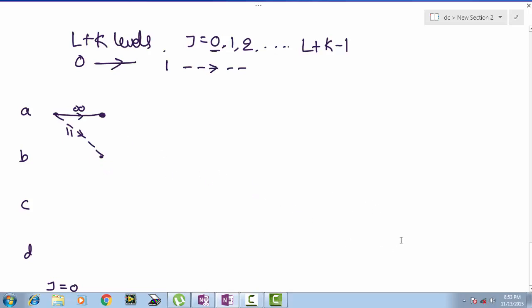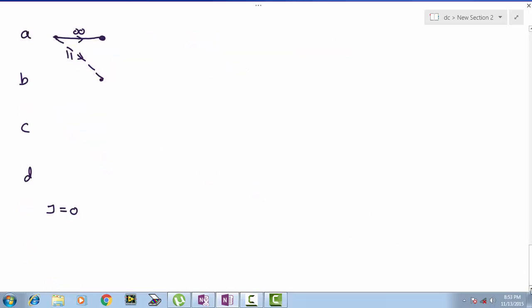Okay, and now by the time we are at first level, j equal to 1, the initial state has been departed to 2 states only. So now again we need to consider input 0 and input 1. When we are in state A, if the input is 0, we move to state A with the output of 0 0. Let us draw state B. When the input is 1, we move to state B with output of 1 1.